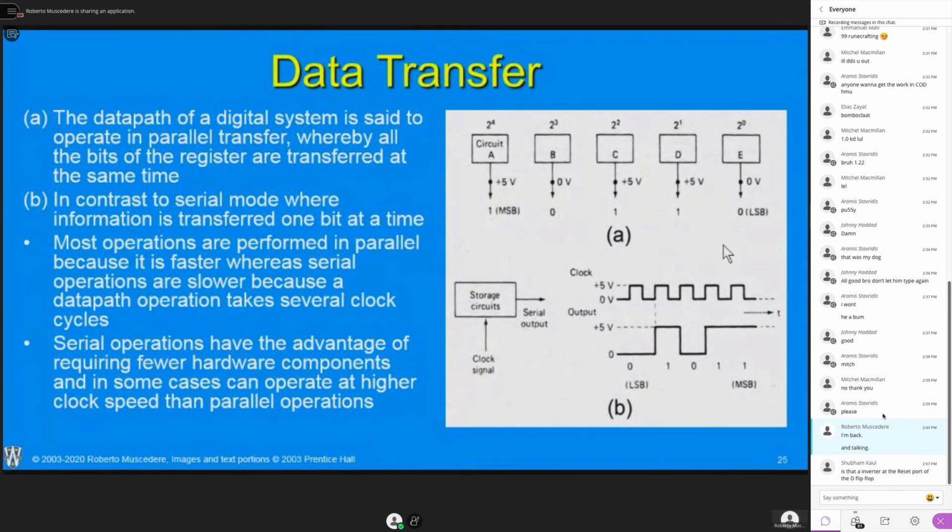Now, that's 5 at best. How does my receiver know when I sent the first one is a question I could ask. How does it know when I sent A initially? I might need another signal for it to realize that, like another signal that says, okay, this is the first bit. So that could add more wiring, or certainly a little bit more overhead. But again, in this case, I either have 5 wires, or in this case, I would have 2.